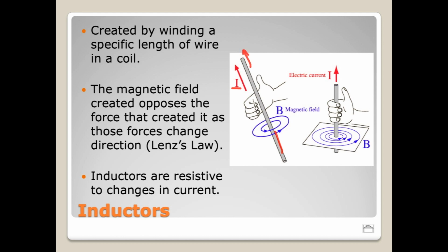Okay. Now remember, with alternating current, not only does the voltage go up and down, but the current actually flows backwards and forwards. So we have current flowing in a specific direction, but it doesn't stay flowing in that direction. It actually reverses, right? So as that current flow reverses, we have this magnetic field already rotating in this direction, but the current's wanting to flow in the opposite direction.